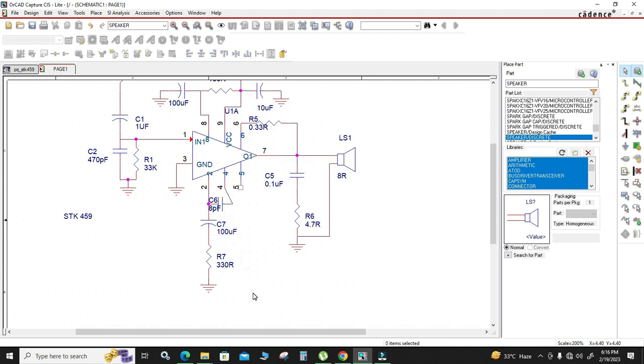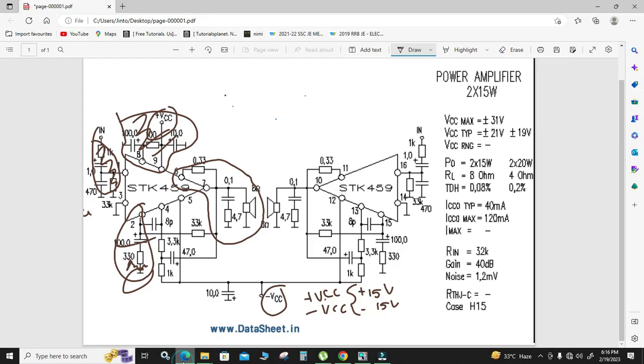Okay, nicely we're done with this connection, pretty good. Then we're going to the feedback circuit. We're done with this connection. It is directly taken from the output. Then we add this 33k. Output to the second pin, feedback by 33k.